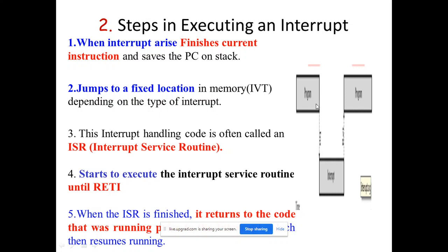At that instant it is showing, for example, that the interrupt arises at 2000. At location 2000 the interrupt arises. So what happens? Your PC status, that is 2000, is held on a stack.